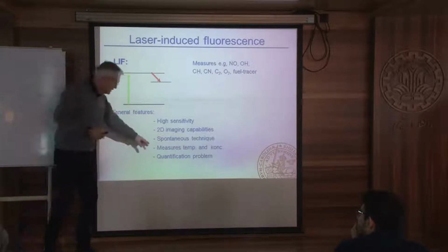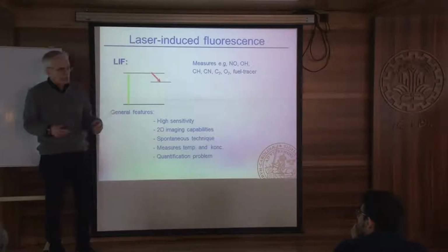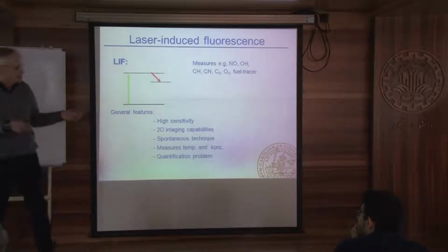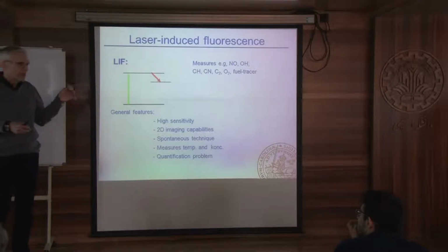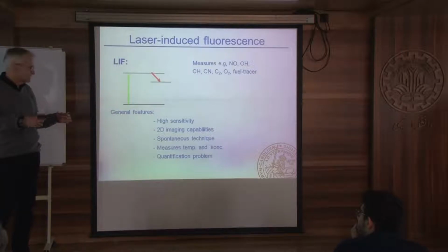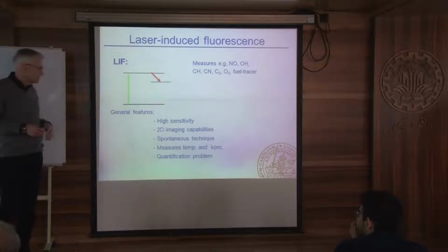But this is, of course, interesting because I think that one of our greatest challenges in the diagnostic community is to come up with a complement to PIV and LDV where you don't need to seed particles. You would like to look at the molecular species. And as I said, we have looked into the possibility to look at the Doppler shift. But that seems to be restricted to on the order of 50 meters per second. So that's not for low velocity experiments. But for high speed velocities, you can do that pretty easily.